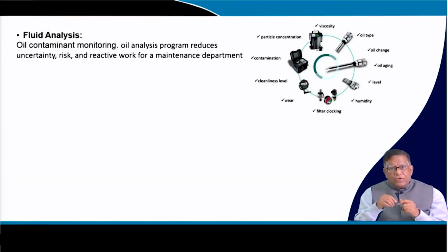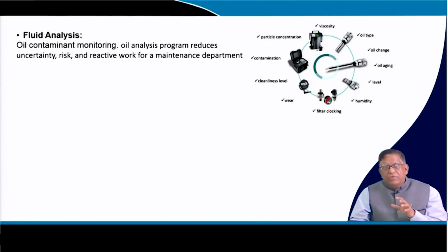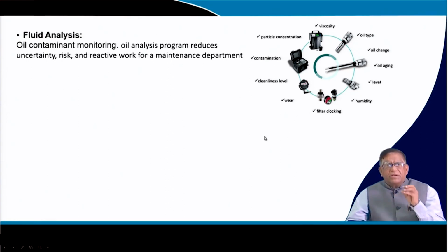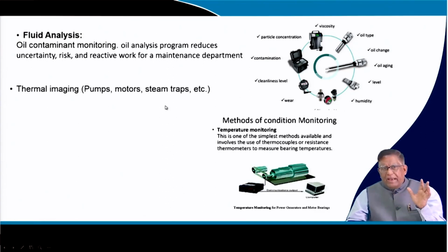Similarly, I told you that fluid analysis will give you a lot of information. You need to know about the lubricant and oil being used: their viscosity, their particle concentrations, how many foreign particles are coming in, what type of contamination, what type of molecules have come in, what the general cleanliness level is, and how the machine is wearing. All these different parameters are determined in fluid analysis.